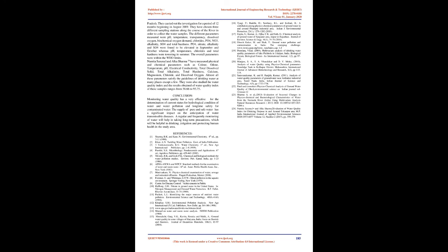Saravanakumar and Ranjith Kumar 2011 present a paper that studies groundwater quality of Ambattur industrial area in Chennai city. They studied parameters such as pH, total alkalinity, total hardness, turbidity, chloride, sulfate, fluoride, total dissolved solids and conductivity. It was observed that there was a slight fluctuation in the physico-chemical parameters among the water samples studied. Comparison of the physico-chemical parameters of the water sample with WHO and ICMR limits showed that the groundwater is highly contaminated and accounts for health hazards for human use.